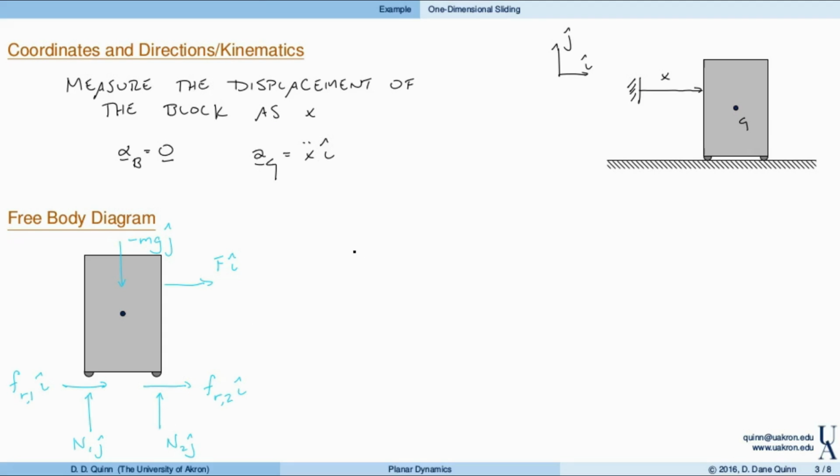So in particular, we define the friction force, so either one of these, Fr1 or Fr2, is minus mu times N, where again N is the appropriate normal load, times the sign of x dot. So this is where the direction of the friction force is introduced.